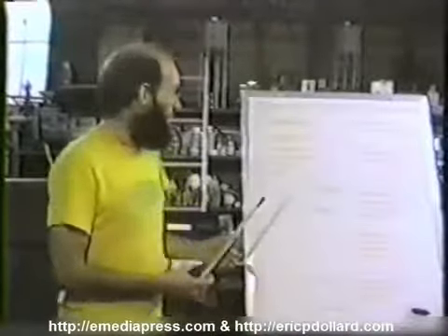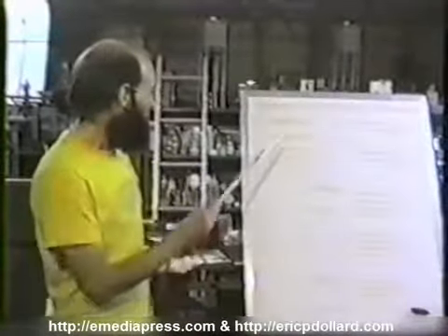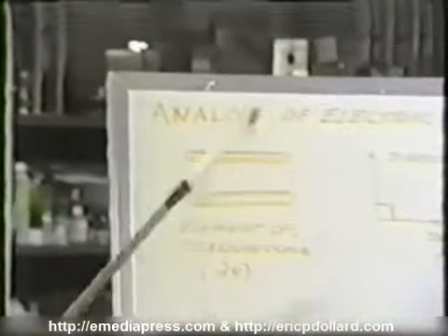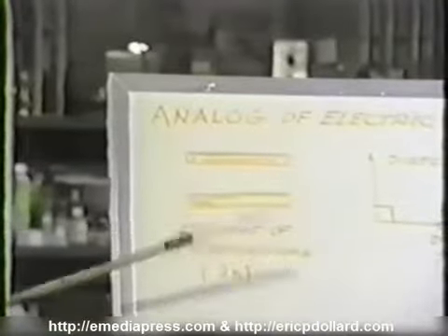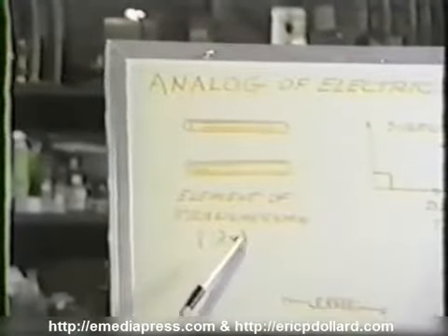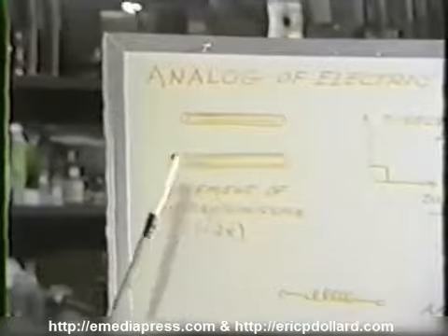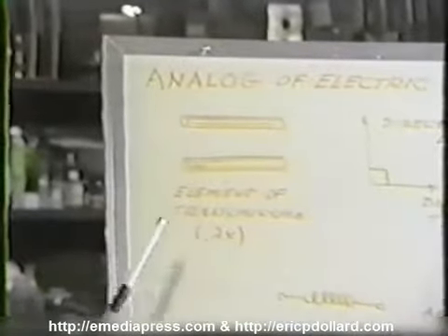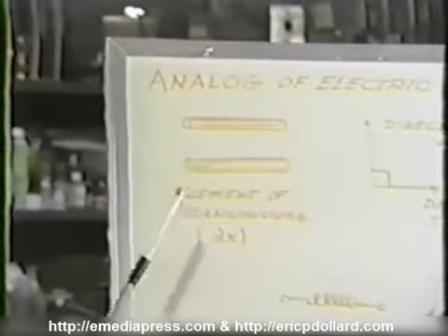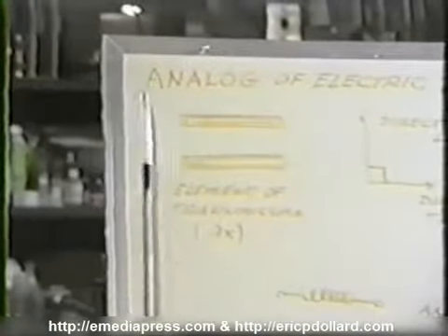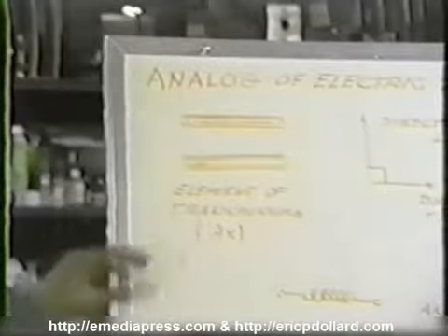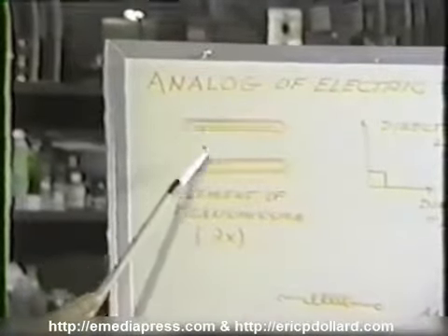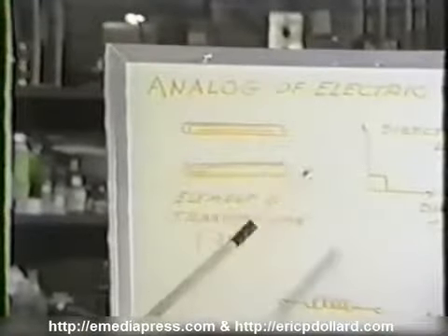Okay, in our analog study of electric waves, we'll start with an element of what we've been working with, which should be one pair of wires. And we'll call this the element of transmission, a differential element, as indicated by this symbol here, of an elemental length, which could be 1 centimeter, 1 inch, 1 foot, or 1 light year, depending upon what you want to take as unit length. So this is a little slice of the transmission section. This can be a little cut out of 2 wires of the coil, or it could be the center wire, this being the shield around the coax.